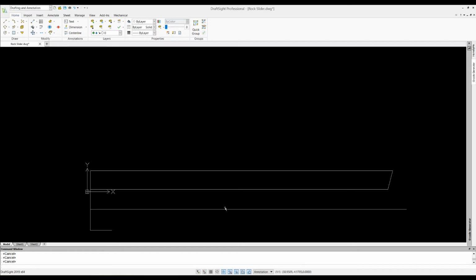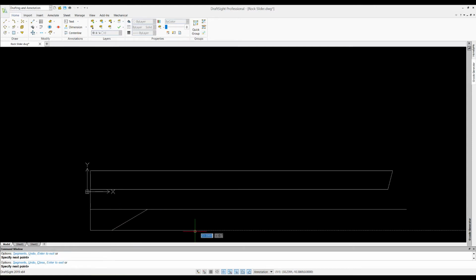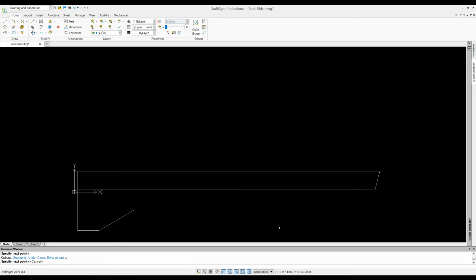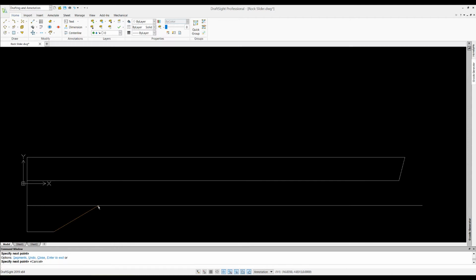So now we have that line. It's really hard to explain this while you're doing it. It almost makes it more difficult, but that's okay. So now that's our 5 3/8 line. So now this is where we can do our 16 over. That's where I should have done it to begin with. So let's go 16, enter, and now connect the dots. Now that's looking better. And now we can, if we wanted, trim this off, but we'll do that in a little bit so that we're not just going into that menu. So now we'll just leave it.